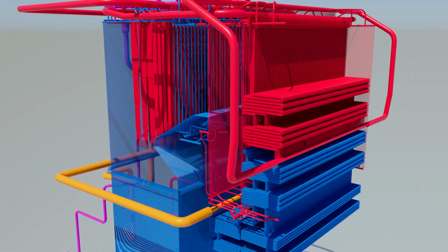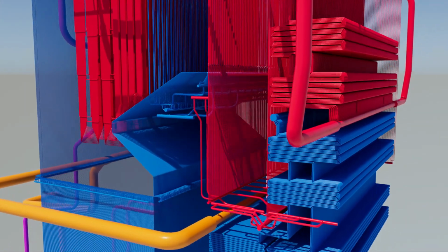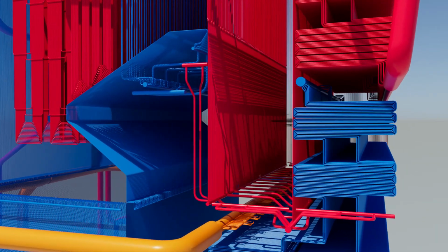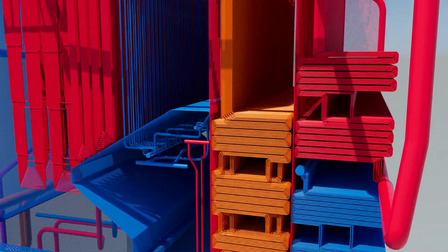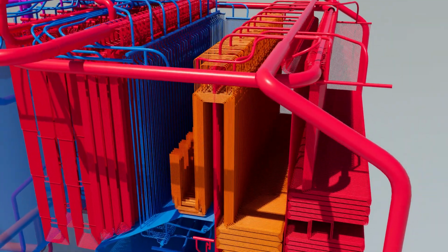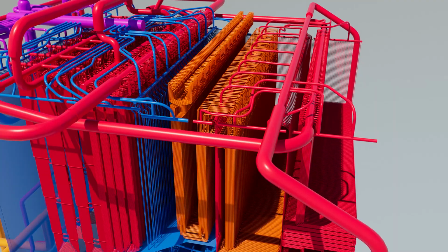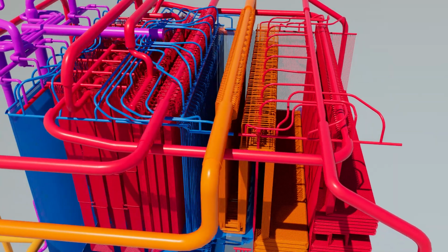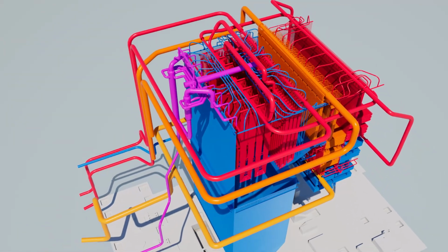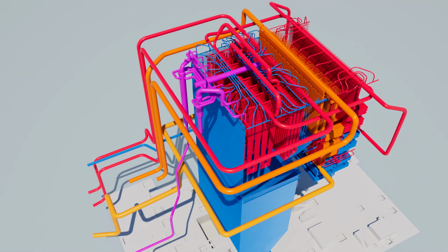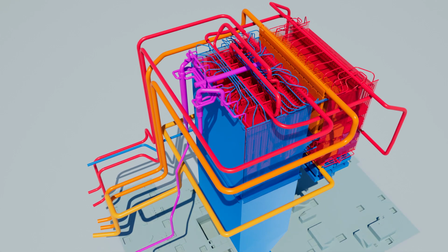The reheater consists of the horizontal tubes at the inlet lower section and the vertical tubes at outlet upper section. It flows upward in the horizontal tubes as a counterflow to the flue gas and flows in the vertical tubes as a counterflow to the flue gas. The hot reheat steam is led to the LP turbine through the hot reheat pipe from the reheater outlet header.